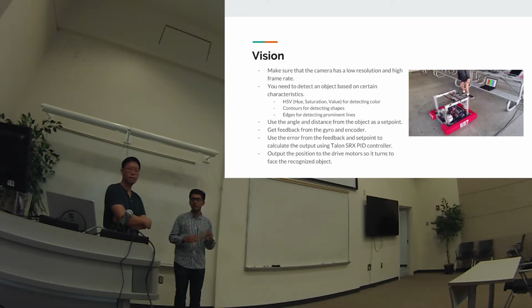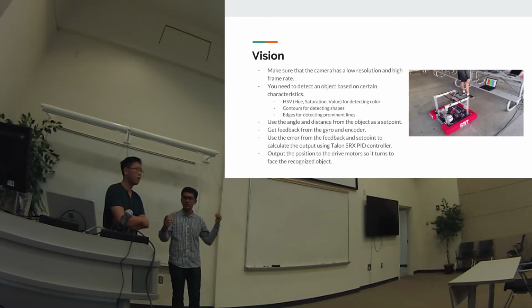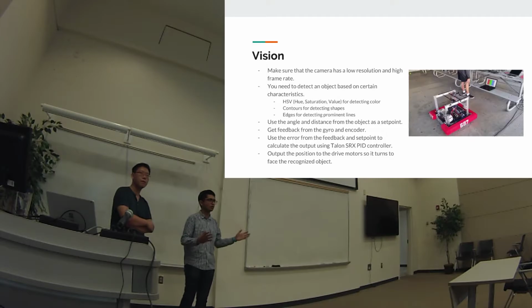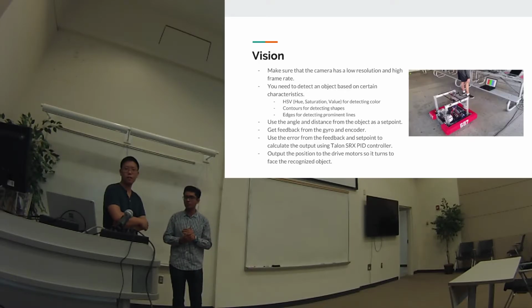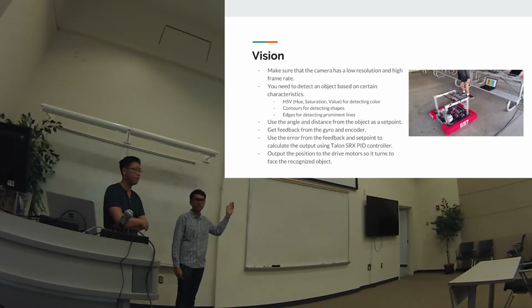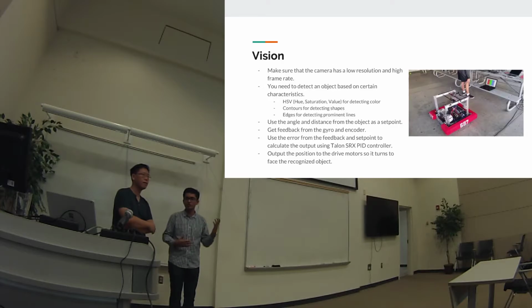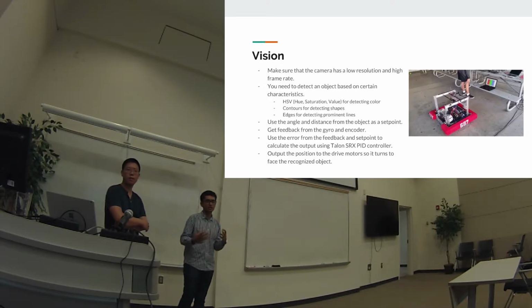So then you can basically go and accurately aim at the desired position using an LED light on the reflective tape. It would detect the HSV. If you're using OpenCV, a computer vision library, if you've heard of it, that allows you to write custom code to do camera vision. So you could also detect things like HSV, that's basically color values using hue, saturation, and then a value, and then that can detect a certain color, like the green light from the reflective tape.